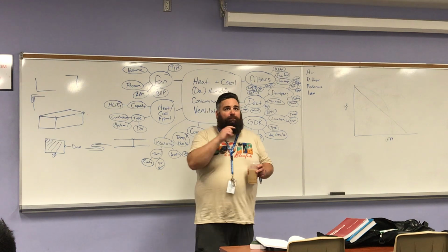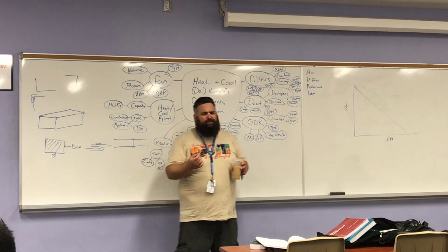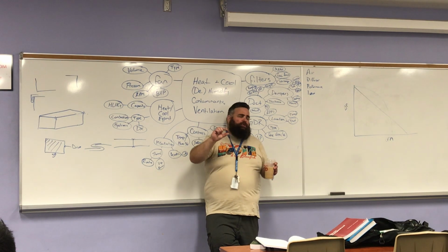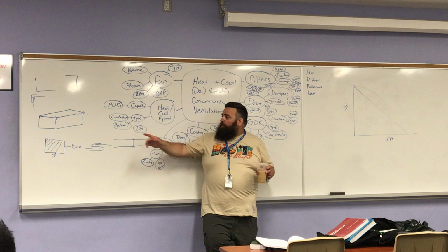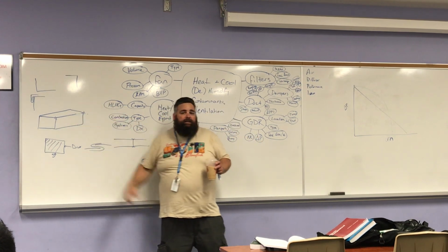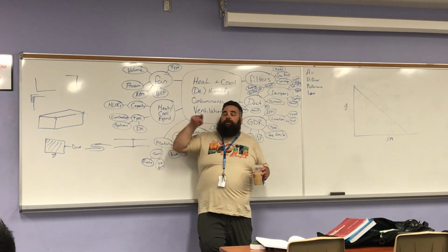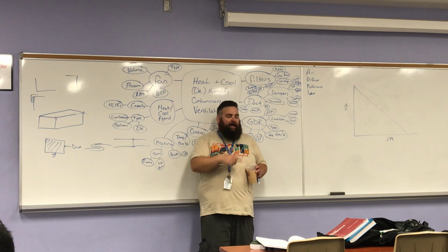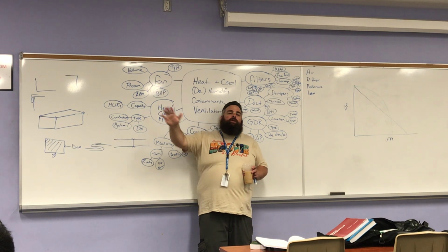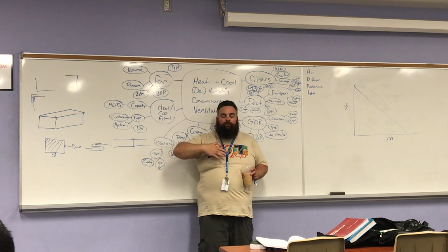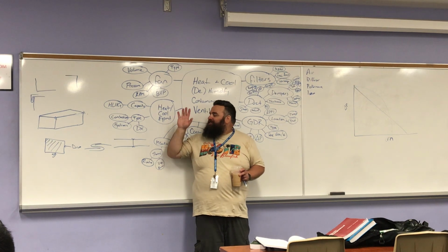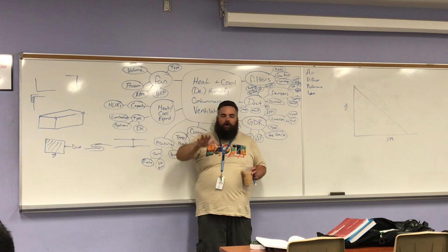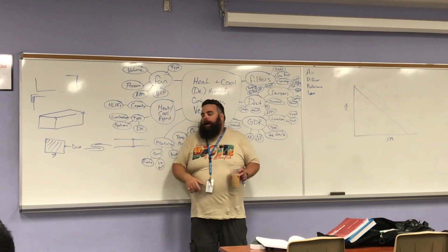It's a fibrous insulation, kind of like fiberglass, but I think it's made out of something different. And you buy it in like 1/2 inch or 1 inch sheets. When they take their L-shaped duct like this, what do they apply? They first weld these little metal pins on it. They spot weld them, right? Exactly, they use a spot welder to put pins in it. They put an adhesive, a glue, that is very noxious, and they put that insulation onto the glue, and then they put these retaining clips onto those tabs that they put on.